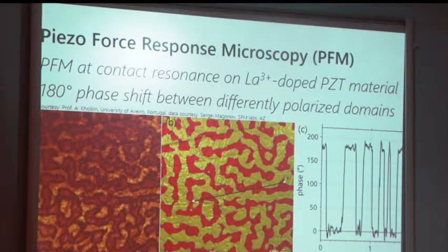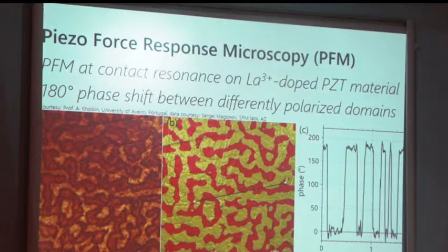If you are working on piezoelectric materials, definitely you can perform piezo response force microscopy and see how the materials expand and contract by applying AC voltage. And if your samples need high voltage, because the standard AFM can apply only plus minus 10 volt, it is also possible to apply higher voltage to the sample, up to 200 volt.